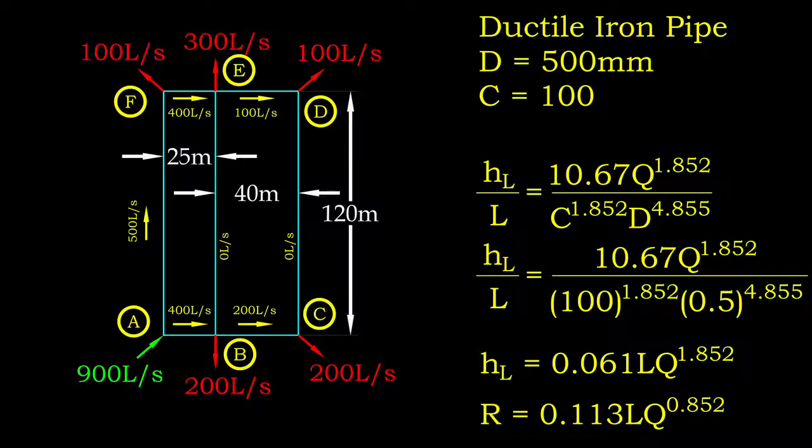Based on the configuration of pipelines, we can establish two flow loops, namely ABEF and BCDE. Next, we set our sign convention for flow direction for loop. By isolating each loop, we set the flow direction as positive if water is flowing in counterclockwise within the loop. Positive flow direction for all pipes is determined and it is referred throughout the analysis.